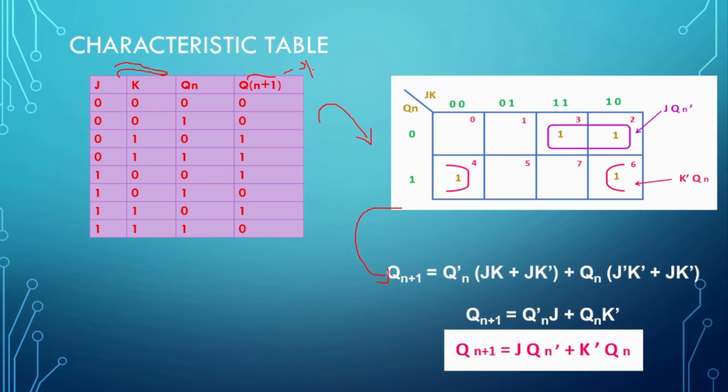If you have three variables, how will you fill this truth table? The first variable is filled with 00001111, the second variable is filled with 00110011 and the third variable is filled with 01010101. Afterwards, you need to find out the output for these variables.